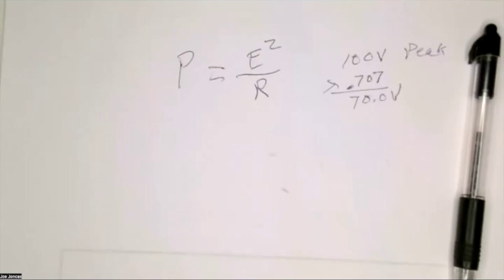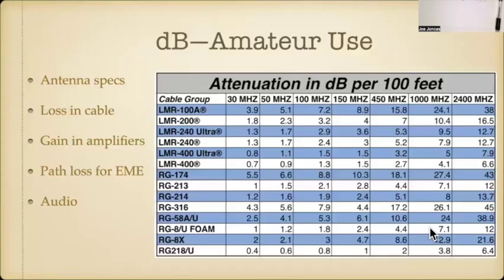Well, I'm using LMR 400 on everything for the satellite antennas and all of that. And I'm using RG 142 inside for all the jumpers because the LMR 400 is so thick and hard to move. Now, why are you using that? So why are you so intense on doing that?